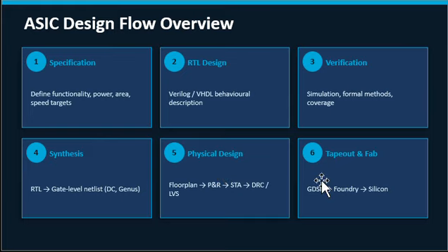Then we go for the tape out after the verification, like our DRC and LVS check is done. Then in the tape out we make a GDS2 file, that is the last file for our tape out. So we'll go through the process in detail now.